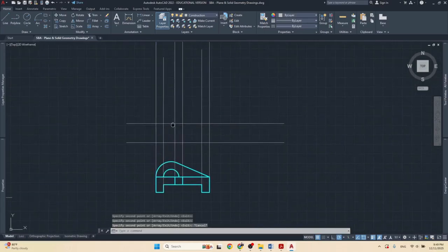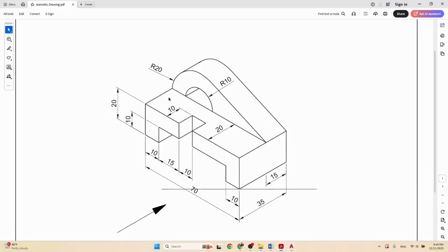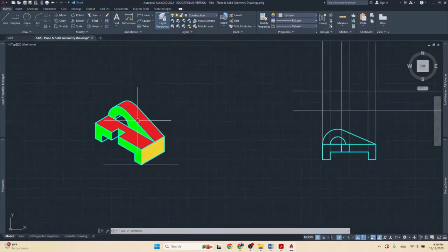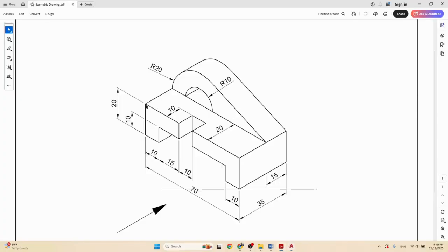So remember, in doing orthographic projection, you should already kind of know what the object is going to look like. So looking from the top, we're going to see this line, then we're going to see it goes in, it's going to come across, come down, then we're going to go across again, it's going to go back and come across, and then we're going to draw the other part. So let's get the measurements. It comes across